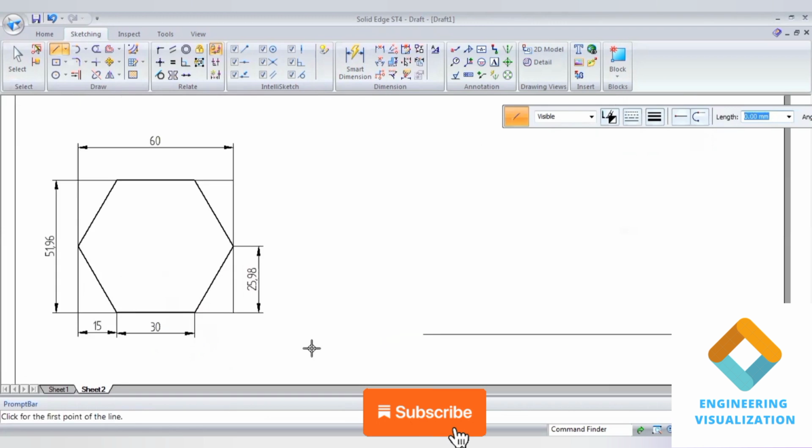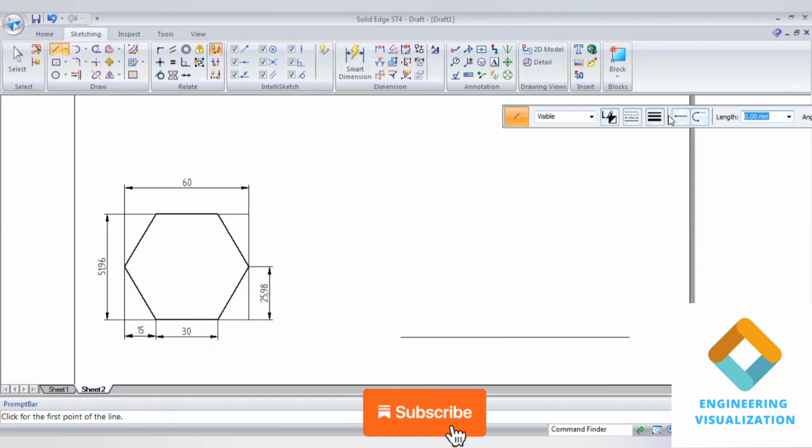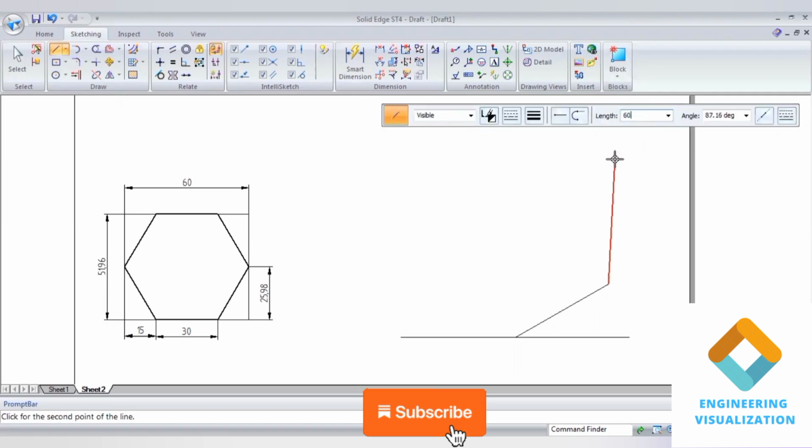Take a reference line. Okay, so from this reference line, construct a box for a length of 51.96, that is the first length, 51.96, and angle 30 degree. Okay, the second length is 60, angle is 150. Again the length is 51.96, angle is 210. Okay, now join. So the box is constructed. Now we have to cut the arcs.